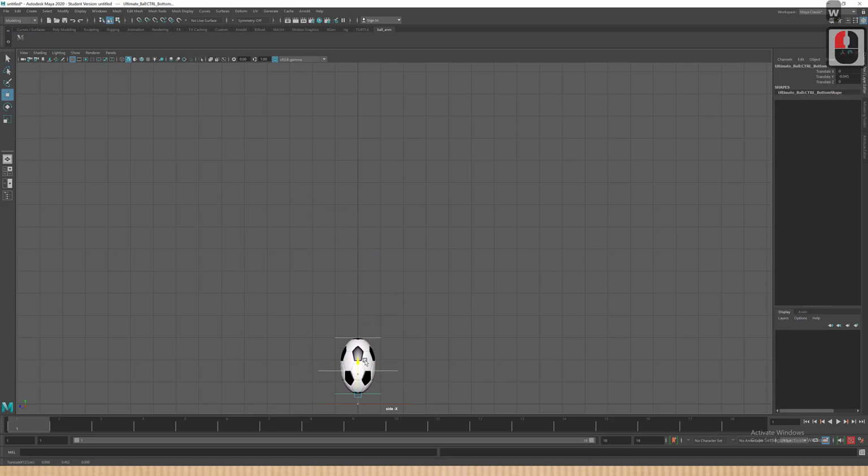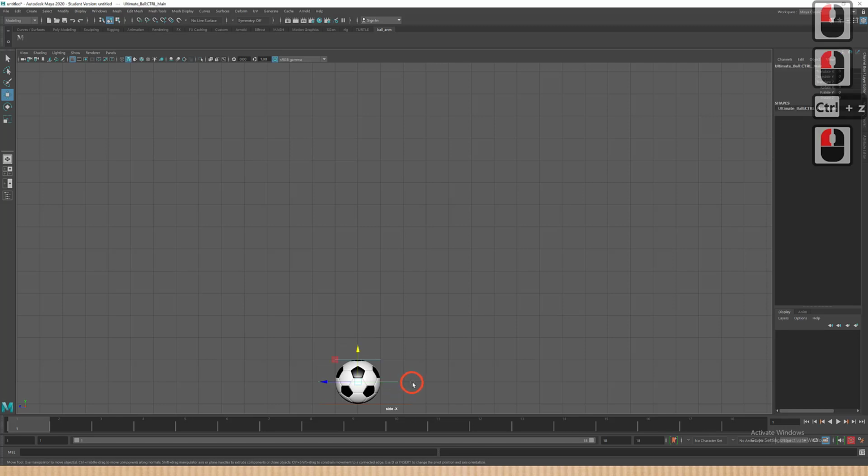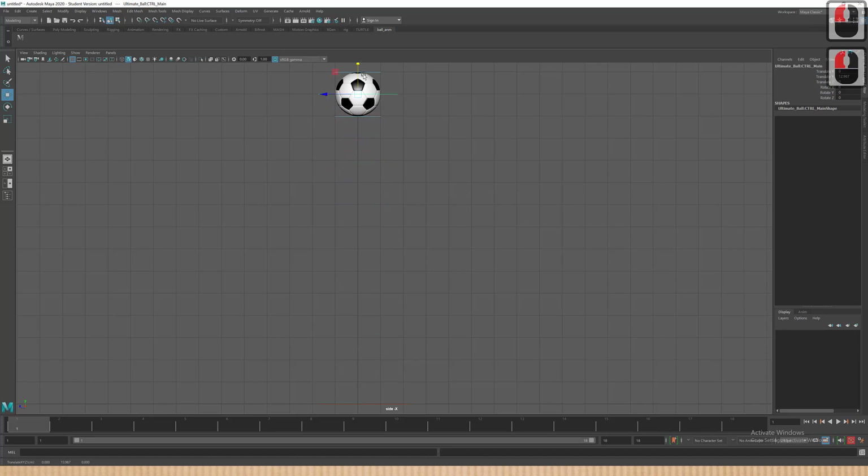Can you see the distortion that's happening in the ball? See to it you never select all the controllers and move your character rigs. It distorts your character rig. The best way is to choose your master controller and take it to the desired position or location, and leave it. Once you are comfortable with the position, select all controllers and just press S. A keyframe has been set.